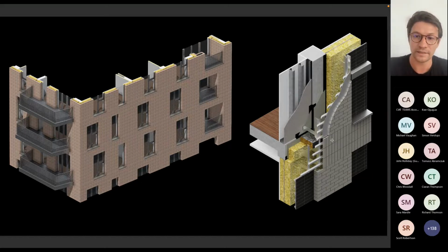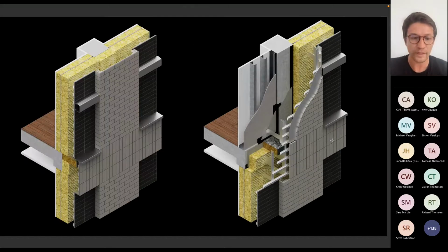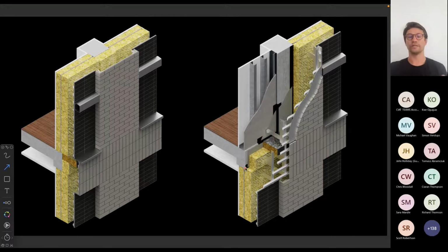In this case here, we do not necessarily need to have this downstand to fit the masonry support. We are treating this as a normal rain screen, and we have brackets and vertical rails running the way we want to, and we can achieve virtually any pattern.